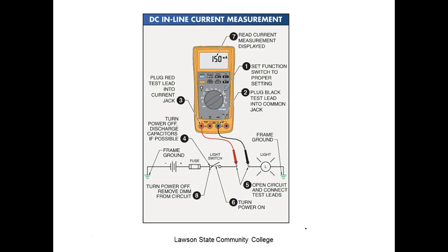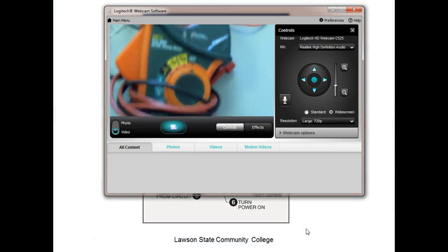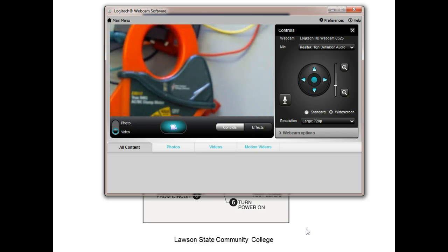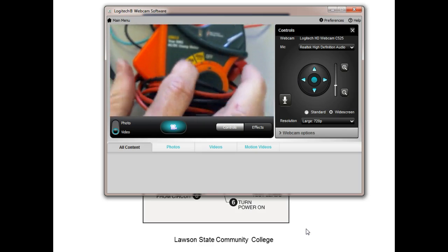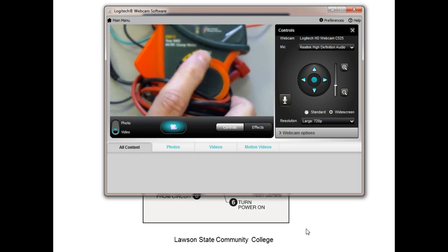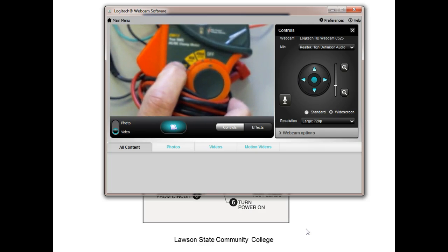Now this is a clamp-on ammeter, which doesn't measure current, it measures the strength of a magnetic field. And the strength of the field is proportional to the current that flows through it. But when you look at the scale for the clamp-on ammeter, if it focuses in, it's 40 amps and 400 amps. So if I tried to measure AC current like 15 milliamps, this guy's going to show zero. So this only works in high current situations, right?